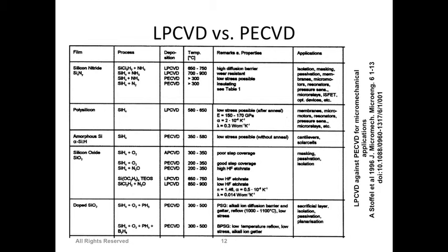There is no plasma generation and no high process vacuum. So you can still achieve depositions in many cases at low temperatures, but the step coverage and quality of film is not very good. That's why we normally prefer PECVD over APCVD. But PECVD and LPCVD are most commonly used.